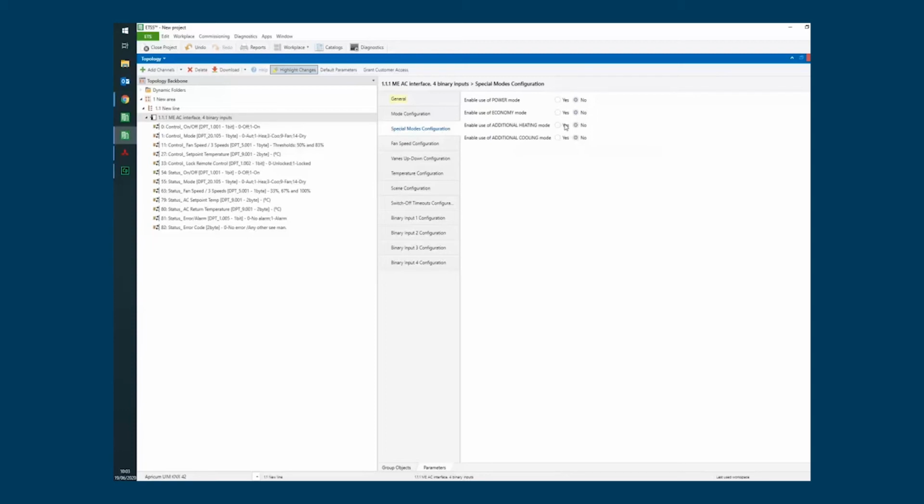In case the heat demand is very high, basically the KNX system should be able to trigger both systems at the same time, and after a while deactivate the secondary system. In that case it would be the air conditioning system. And for this purpose, we have included this function. Basically, there are two ways, again, to manage this type of additional heating and additional cooling.